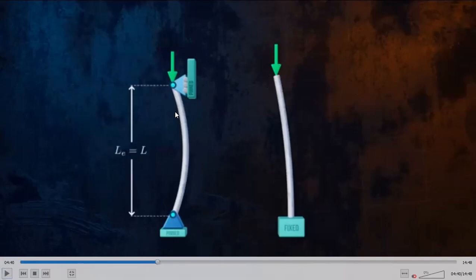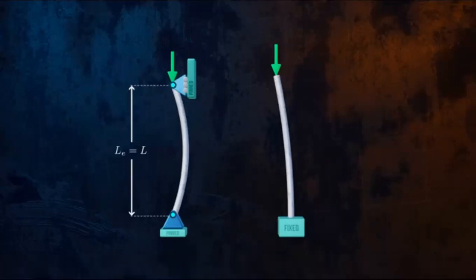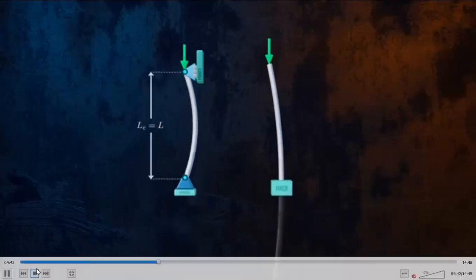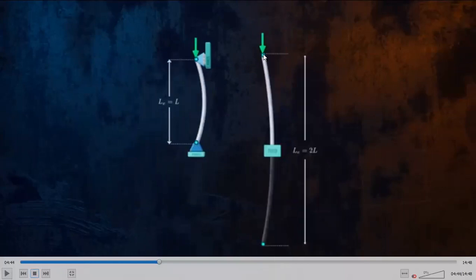As I told you, the effective length means the distance between zero bending moments. You can set this into an imaginary length until the inflection point is obtained. At the free end, you know the moment is zero, so you take the mirror image. So your effective length will be 2L.